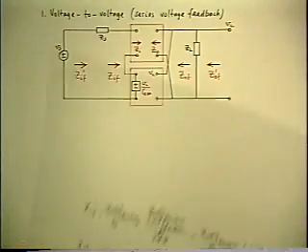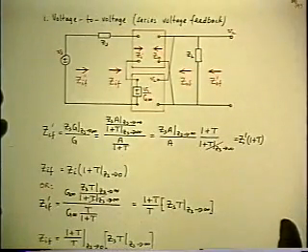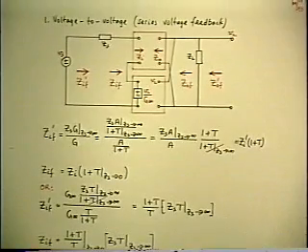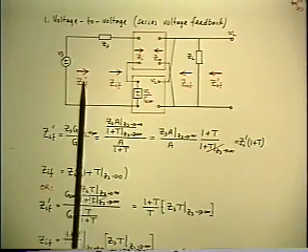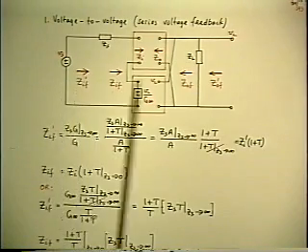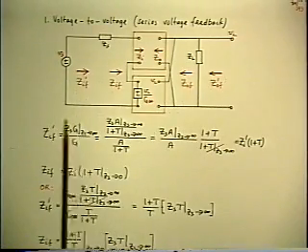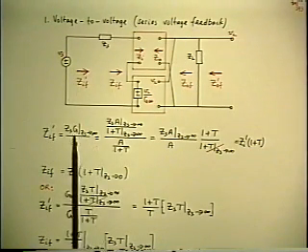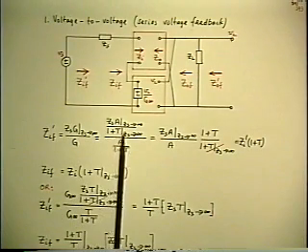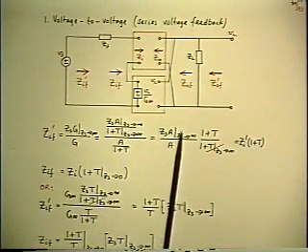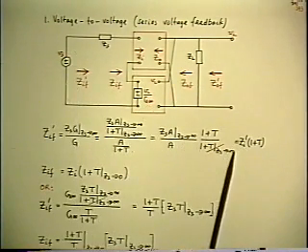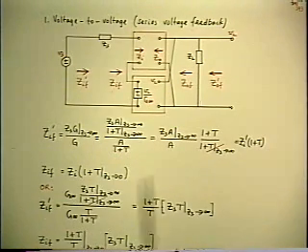Now let's do the same thing for input impedance. We've already leaned on the duality more than once, and we're going to lean on it even more in the next few pictures. Suppose we want to know the outside input impedance of the amplifier with feedback. This is the formula we've already established. So all you do is substitute for G equals A over 1 plus T, take the limits factor by factor, group the A terms together, and identify them as the outside input impedance before feedback, Zi prime.